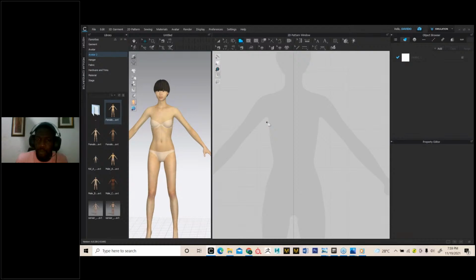So to activate your polygon tool, after selecting it, you left click. Then you don't leave it, you go to the next point you want it to be, you left click. Again, you left click. You left click. You can go down. All right, this shape I'm doing is not fine at all, but I'm just doing it to explain how this tool works. You can go like this, you can go this way.